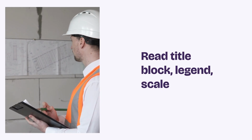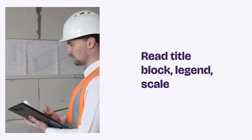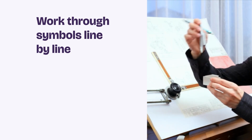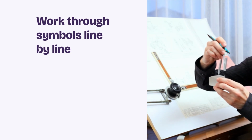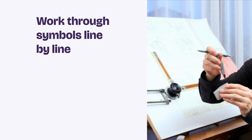Start by orienting yourself. Read the title block, review the legend, check the scale. Study the floor plan, then move to elevations and sections. Work through the symbols line by line, comparing them with the legend until the meanings become second nature.